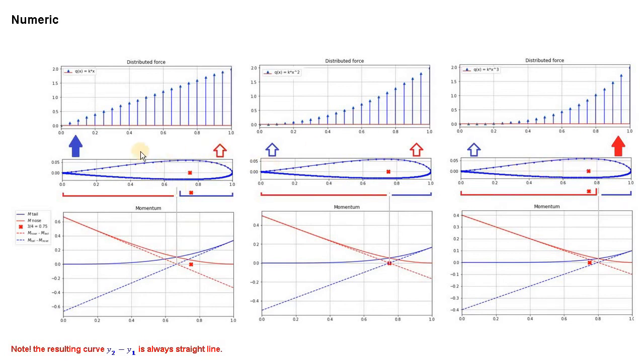Different airfoils have different distribution of pressure, and as a result you're going to have different position of the point at which you have the 0 momentum. And the only one thing you have to keep in mind is to place center of gravity exactly at this point. So if you change the angle of attack, this point is going to move probably a bit, so you just pick the operational point and pick the angle of attack that you're going to operate most of the time, and in this place you're going to choose the position at which you have the zero momentum position for the center of gravity.